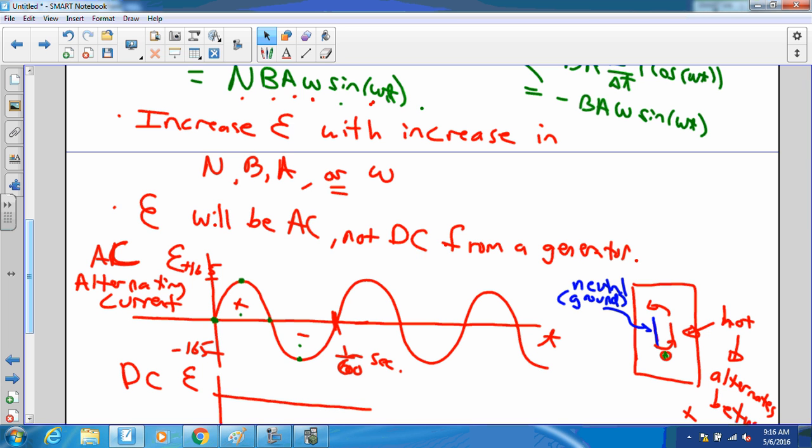And the reason was really simple. My electric guitar had, if you know what quarter-inch cables look like, the tip is the hot, and then the shaft right there is the ground. And so I was plugged into ground on my amp. His amp was grounded, and for whatever reason, the ground was at a different level. Obviously more than 40 volts difference, because that's the threshold of being able to feel it. And so I sat on that and was essentially conducting current through my rear end.